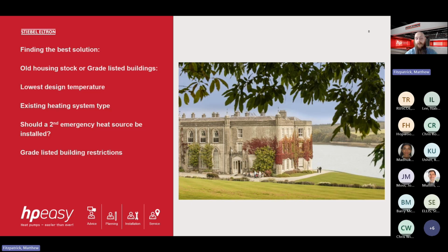And ground source heat pumps are normally the easiest because they can go inside an existing plant room, and the ground collectors will go out into the ground a metre to a metre and a half below, completely hidden in this example, and it's not visible. In the Plasnow example, because it's extracting from the Menai Straits, there's a floating pontoon which rises and falls with the tide, and that's not visible as well.